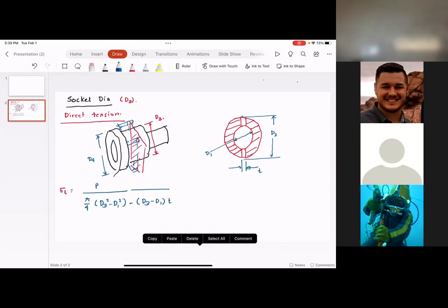Everyone understood the logic behind this? So when we look at failure, there are two ways. One is the deflection-based failure, and the other one is the strength-based failure. Quarter has failed, what that means is the quarter has actually sheared, basically fractured. That is one type of failure. The other type of failure that we can see is the quarter has bent. But even though the quarter is bent in this particular assembly, that assembly could still function.